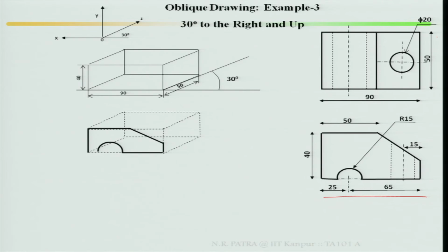The front face or front view in the oblique view is your true shape. So whatever the dimensions are, it is in true shape. Then go to the depth direction, then finish your slanted face. Up to this you finish it off, take it out.